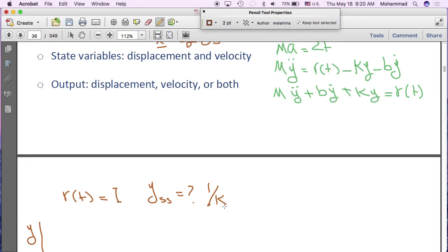That's a good question. That equals 0. Why? That's what we did in the previous example. Why? Steady state, it's built into it. Steady state means when y will be constant, not changing with time anymore. We call that instant steady state, and at that instant and onward, y dot is 0, no velocity. That's the meaning of a mass being motionless: its velocity is 0. And so is its acceleration, because if acceleration is not 0, even though velocity is 0, it will change.